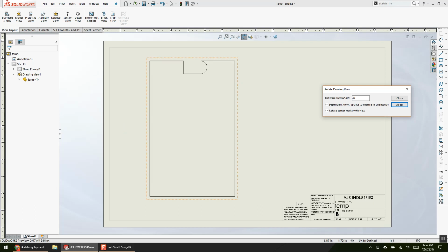So, my opinion in my class, if you give me a print like that, you're going to get points off because that's a bad print. No mill operator is going to put that like that in their mill. So they're now going to take your print and rotate it, and now everything is on its side because that's how it fits into their part, and they're going to match up the dimensions. Right? So the print is exclusively focused on giving manufacturing what they need. Nothing more, nothing less. So we have to think about that.